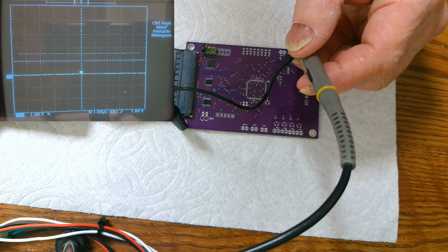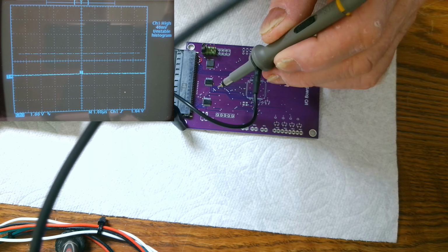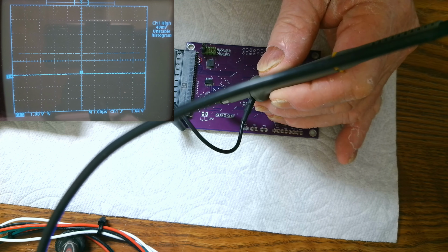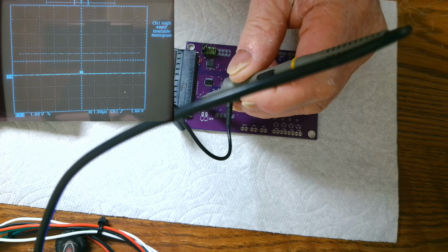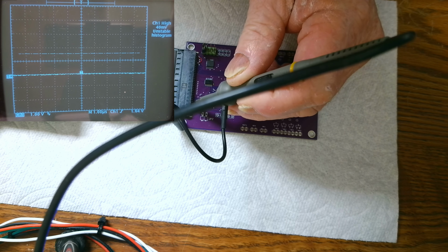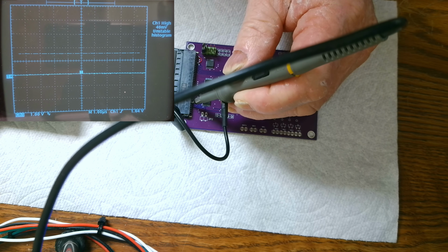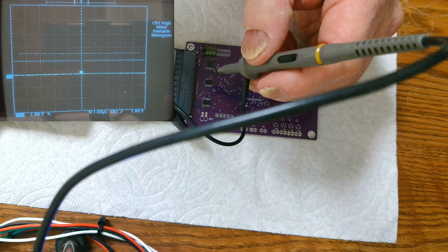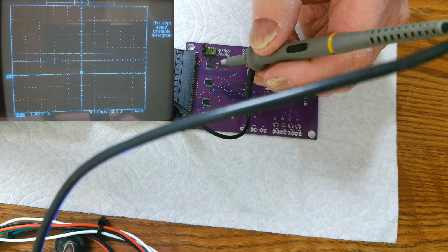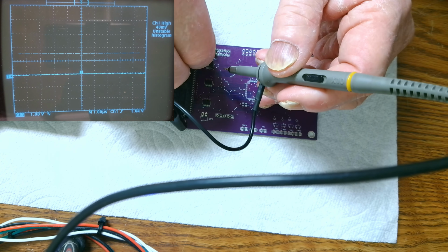So we should check the 2 buffers on the top here because they're for the address. And I'm pretty sure I can see the traces here. So everything is low. Low. So they should be selected. Let's move our jumper and see what they look like.